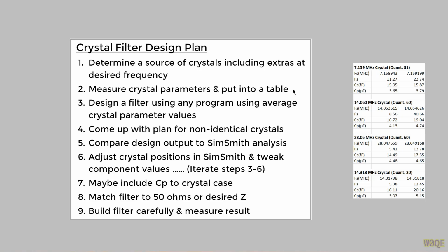Third, you need to design a filter using any program that you wish. And the program is going to ask you for the values of the crystal, and you need to put in some kind of average of what you think the value is from what you've scanned in the crystals you're going to use. This is not a big decision to make. Just roughly come up with an average and use that as a starting place.